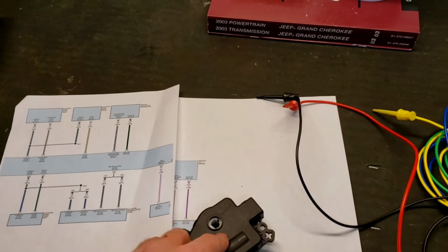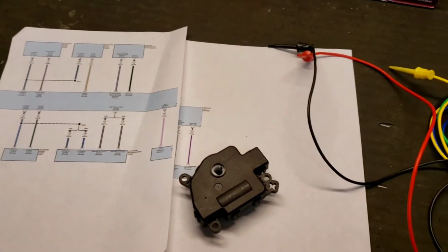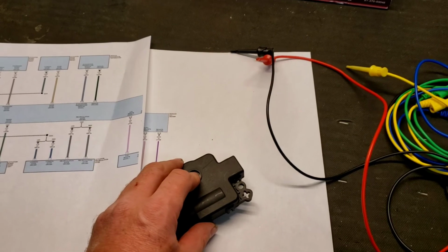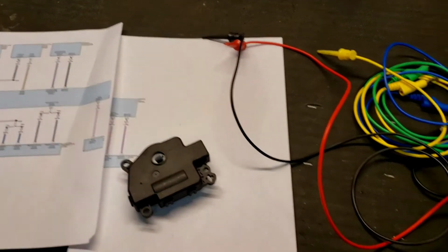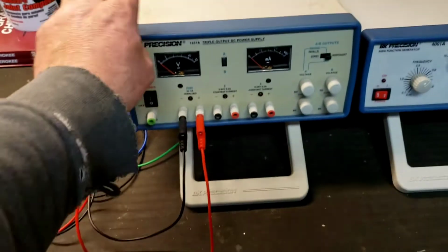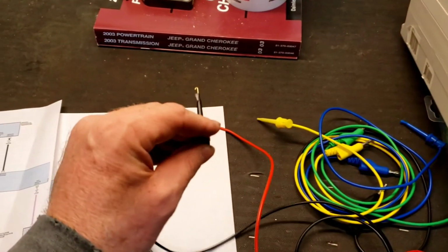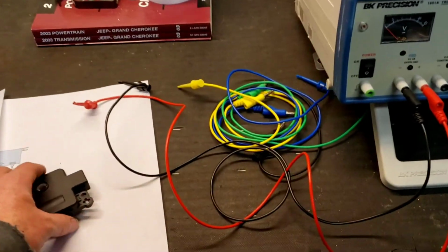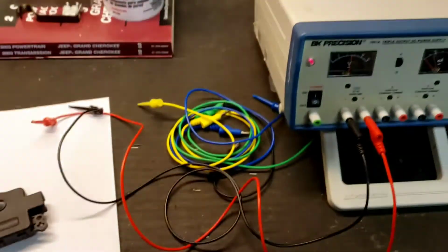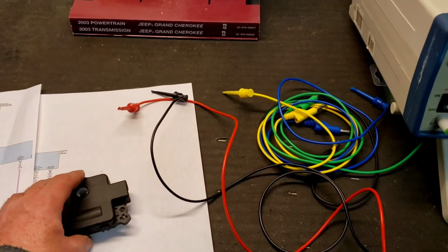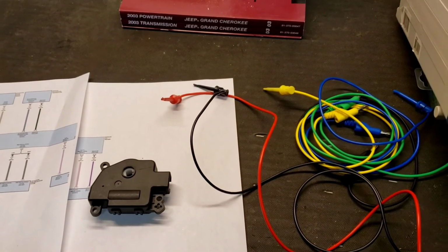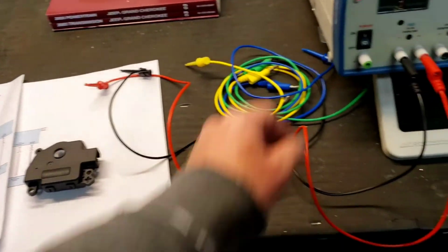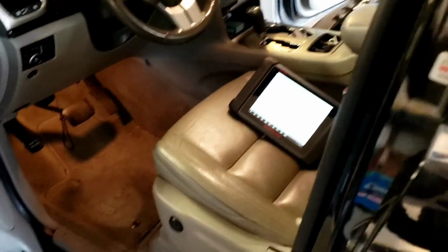How does it know when to stop? It reads amperage back through the module here. Well, if this is flexing, it's stopping, but it knows that it's out of its specifications. Not only that, it was acting real funky when I hooked up the DC power supply with my leads. I can move it with the power supply, hooking these up, but it doesn't really handle much of a load for amperage, obviously. So that is it for this 2012 Jeep Grand Cherokee.